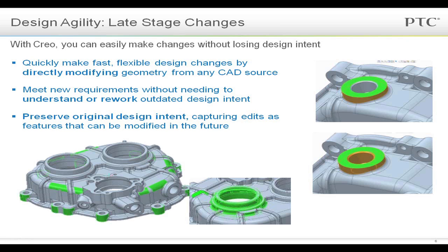Now when we're laying down features in Creo Parametric, you're already building that intelligence. You're building a formula which results in geometry. So for you old school users out there, you'd say, right, I want a protrusion, it's going to be one side, it's going to be from this datum plane. I'm going to sketch something, I'll extrude it by this distance, I'll add taper, etc. So you're building a formula which results in geometry.